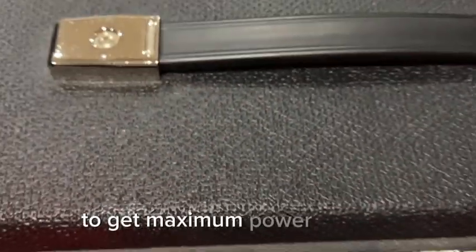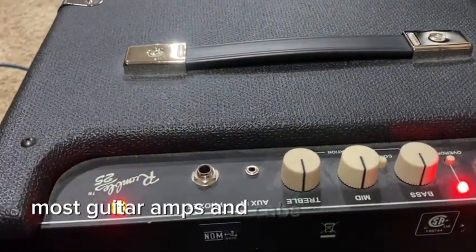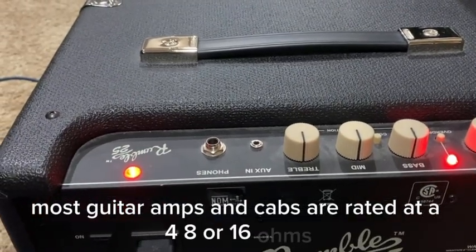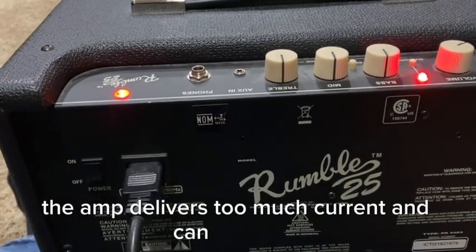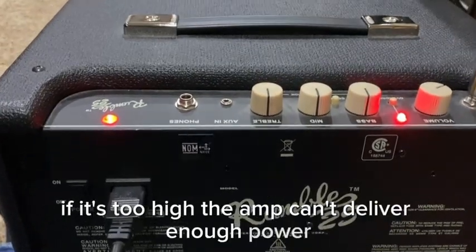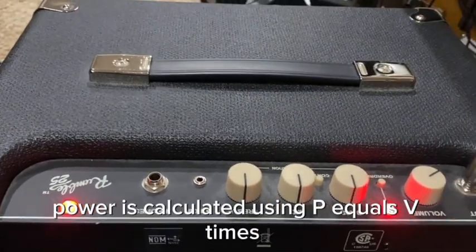To get maximum power transfer, the amplifier and speaker need matching impedance. Most guitar amps and cabs are rated at 4, 8, or 16 ohms. If the impedance is too low, the amp delivers too much current and can overheat. If it's too high, the amp can't deliver enough power, resulting in low volume. Power is calculated using P equals V times I.